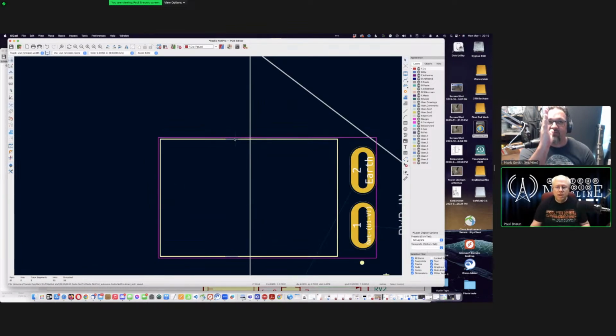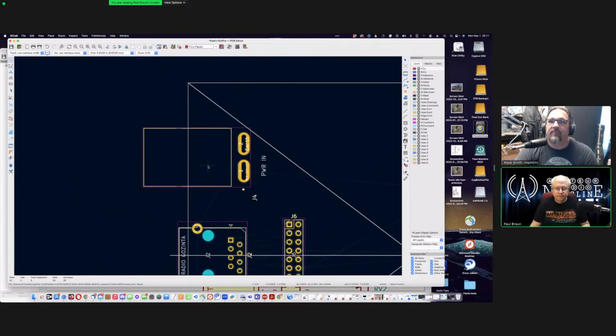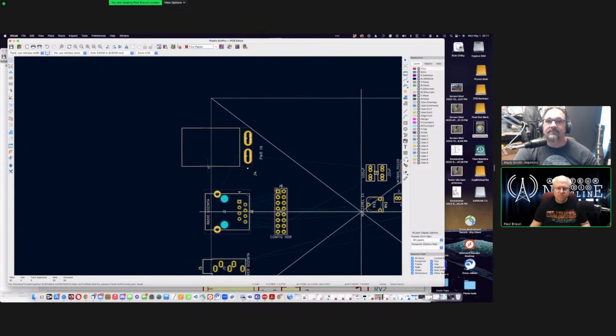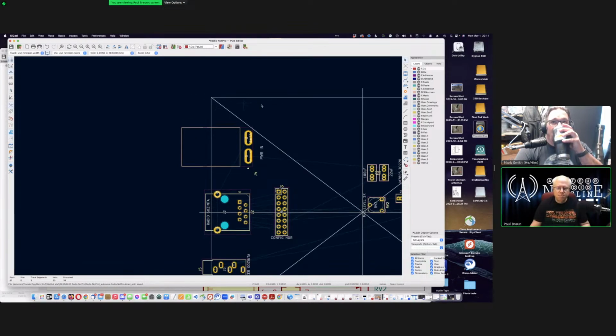Because remember, you're going to have another board width as your panel. Okay, so here's the edge of the gray. That's probably good enough. And I probably want to drop that down a little bit because we've got box edge, board edge here. It's got to be 2 millimeters away from the edge. You're way more than 2 millimeters away from the edge. Oh, okay. All right.